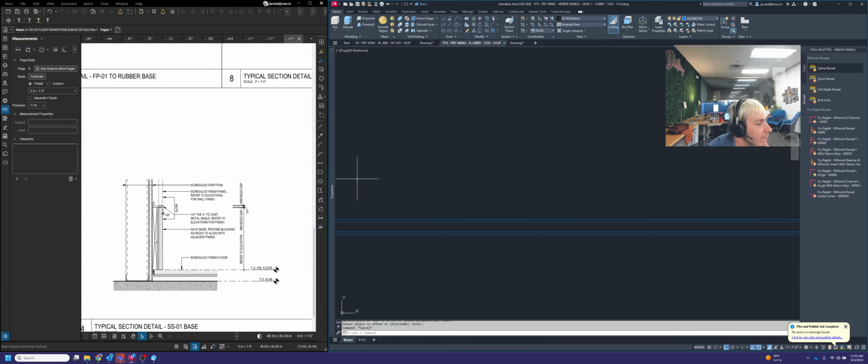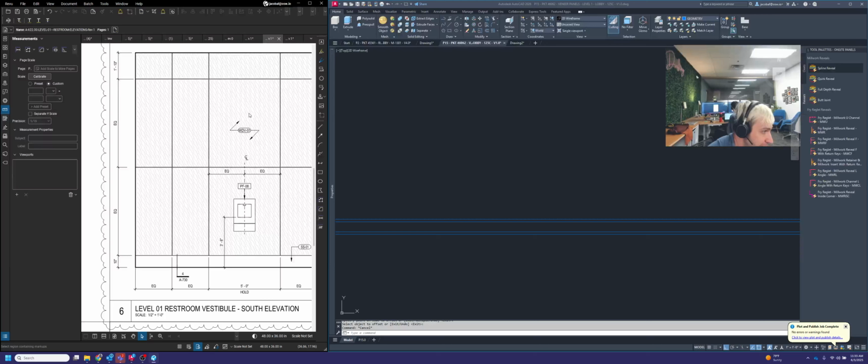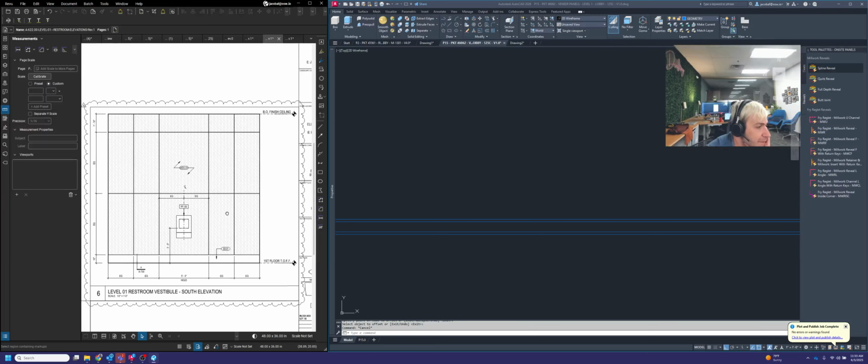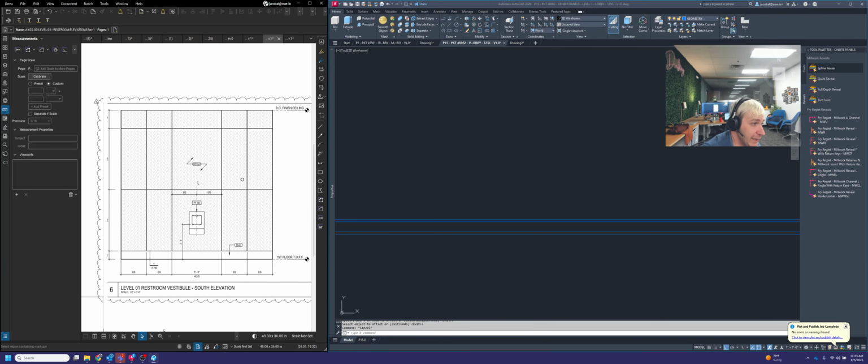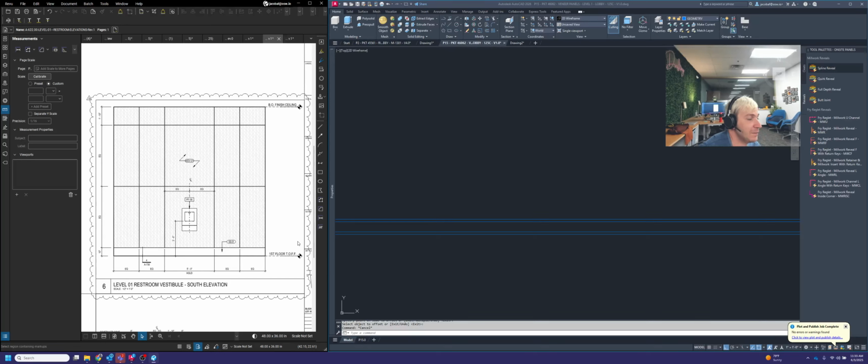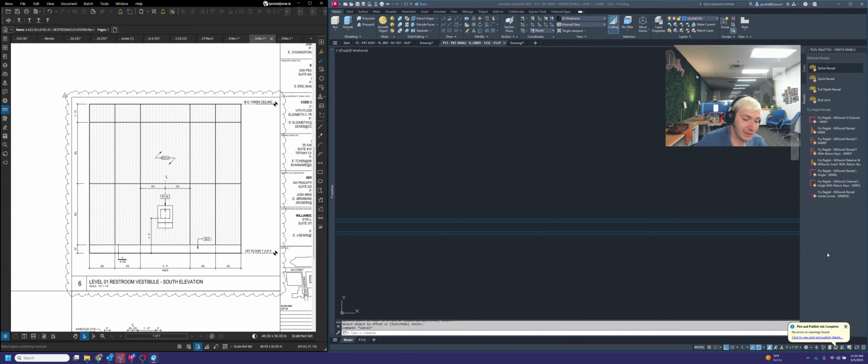Okay. Now let's go back to our elevation view again and see what we're dealing with. So at the very top, we have a panel that's 1'10", so 22 inches tall. And then we have 2 equal panels in the middle. What we need to do is verify what the ceiling height is. It is not given to us here on this drawing, but an excellent place you can look to find that is going to be your reflected ceiling plan. So the reflected ceiling plan will be in the job folder.